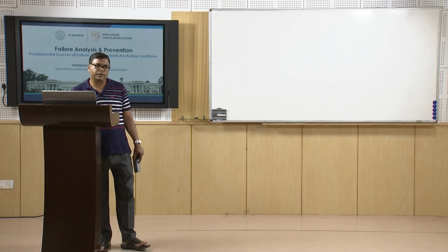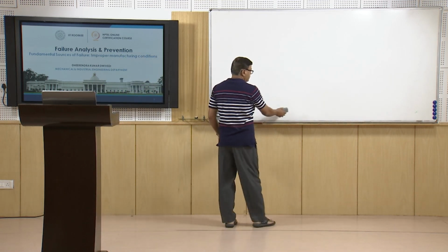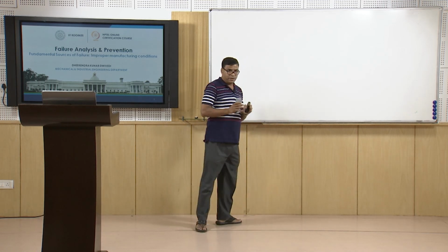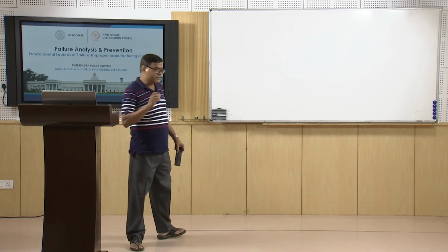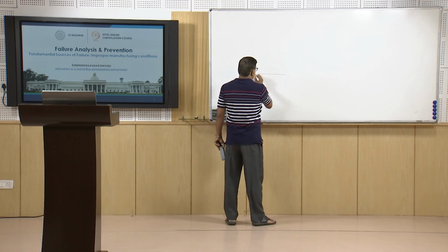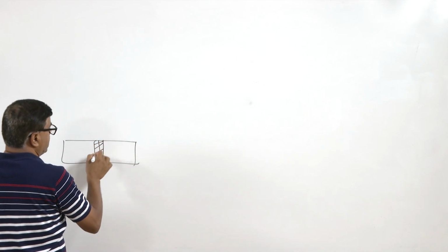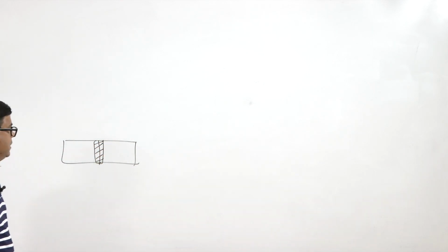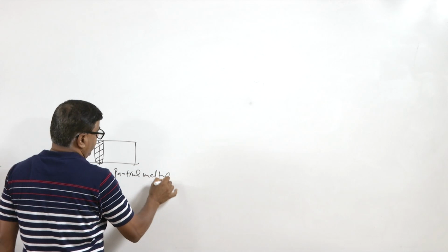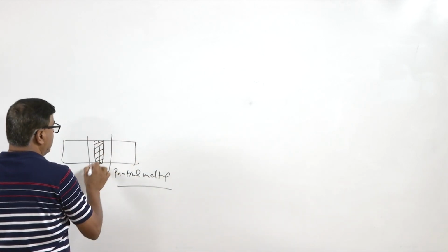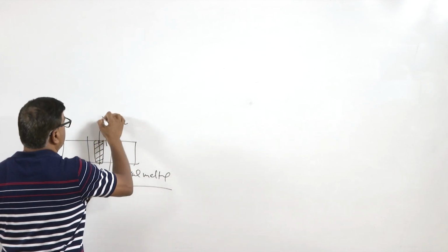We know that for welding there are three types of approaches which are used for joining purposes. One is where the edges of the components to be joined are brought to the molten state, meaning the faying surfaces are brought to the molten state like this, like the two components. So, edges will be brought to the molten state, and after solidification we will get the metallic continuity. So, basically it involves partial melting which is coupled with heat affected zone formation. So, base metal, HAZ formation and the weld metal.